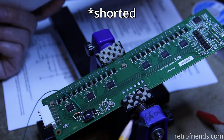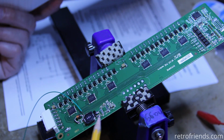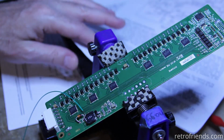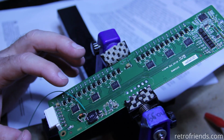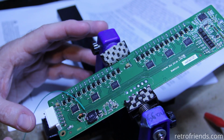So I didn't have any SMDs, but I did have a Schottky diode, so I put that one in there. And I got the genius idea that, with the chip removed, I could power this board because I know where the 5 volts needs to be.